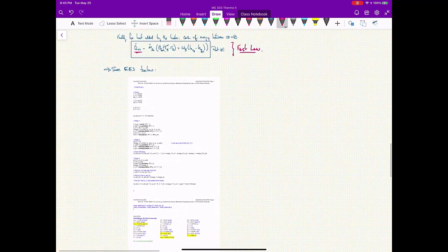I just wanted to go over this solution process with you, because it's not necessarily completely obvious looking at the solution in PDF form straight off the bat. But hopefully this demystifies the psychrometrics aspect a little bit for you. To summarize everything, all that I did over here is apply first law between individual processes, 1 and 2 specifically, and then separately for part D between 2 and 3.